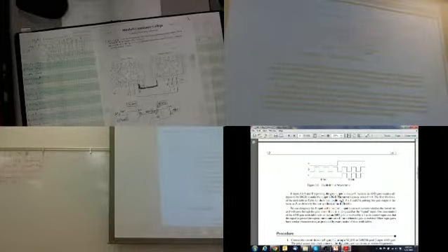Once it boots up, I would hit the default setup. Default setup, and show you what happens. It puts it into just standard mode. Okay, that's what it's going to look like. Now, one quick and easy cheater way to get this thing to work is connect this. Put this on about a 10 kilohertz signal. So you select 20K and you set this to 10.